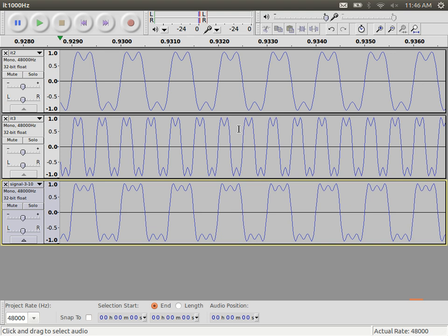The other thing, A has a bandwidth of 2,000 hertz, B has a bandwidth of 4,000 hertz. The higher the bandwidth, normally the higher the cost of the device and of using that spectrum. Because the range of frequencies we have available to transmit is limited. Therefore, the more you use, the less other people can use. And therefore, there's competition to get access to the bandwidth, and essentially, in most cases, you need to pay a license to use a particular set of frequencies. And the more you want to use, the higher it costs.